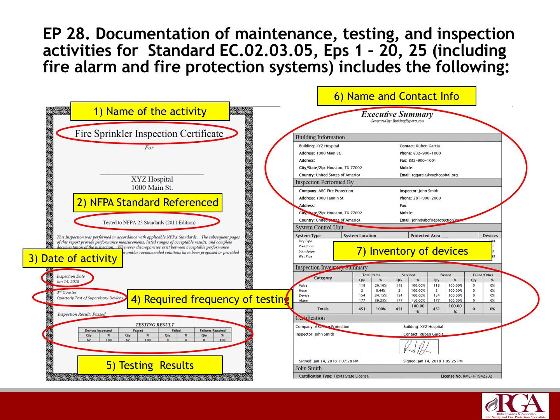That is, if you have 1,000 smoke detectors, your report better show all 1,000 smoke detectors with the pass or fail criteria, whether they passed or failed. So the inventory of devices is important, because otherwise, how else could you confirm or verify to the surveyor that you've actually tested every single device? And that goes for your fire alarm interfaces, your relays, your kitchen hood system. When that goes off, that sets off a general fire alarm signal that says, hey, your kitchen hood has been activated. They'll look through your report and try to scour through it and find that specific alarm point.